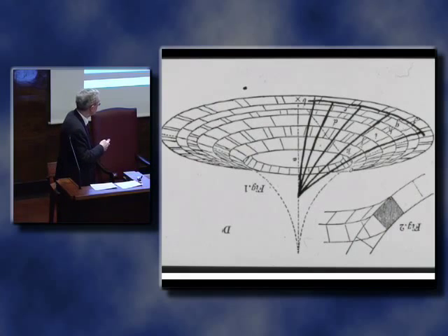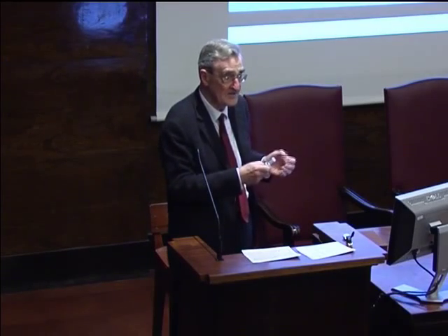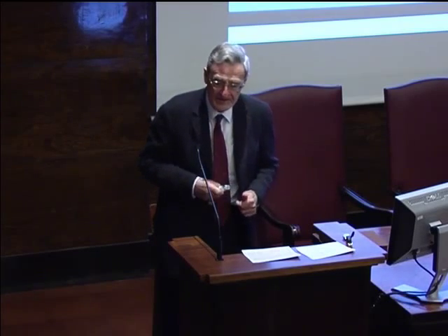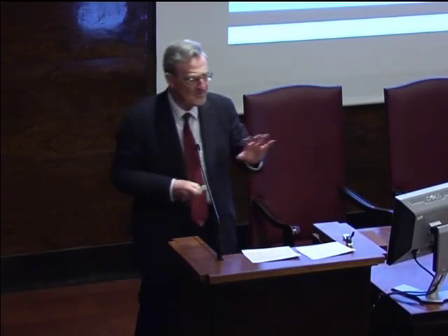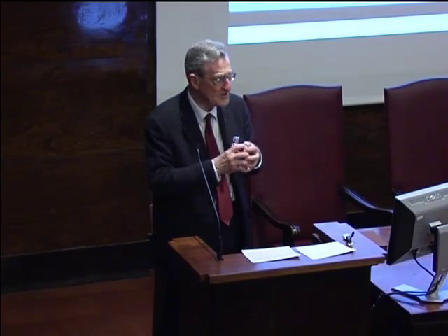And there is no escaping from the fact that in order to build such a structure, every stone you place must be supported from below until fans meet each other on the opposite side of the church and can push against each other and so generate these compressive forces. What I'm saying is, just as for the two-dimensional arch built across a river, you have to have centering until the keystone is in place.